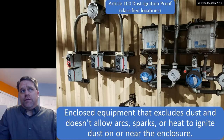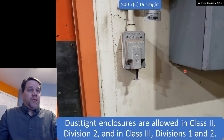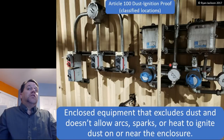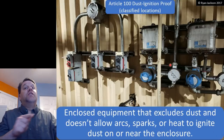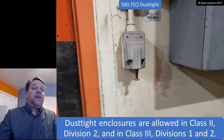That's dust ignition proof. Compare that to dust tight, which is very different. Dust tight is simple. Dust tight enclosures are allowed in Class 2 Division 2 and in Class 3 Divisions 1 and 2. And by the way, I didn't say this, but dust ignition proof is allowed in Class 3. Dust tight is also allowed in Class 3. Dust tight is also allowed in Class 2 Division 2.